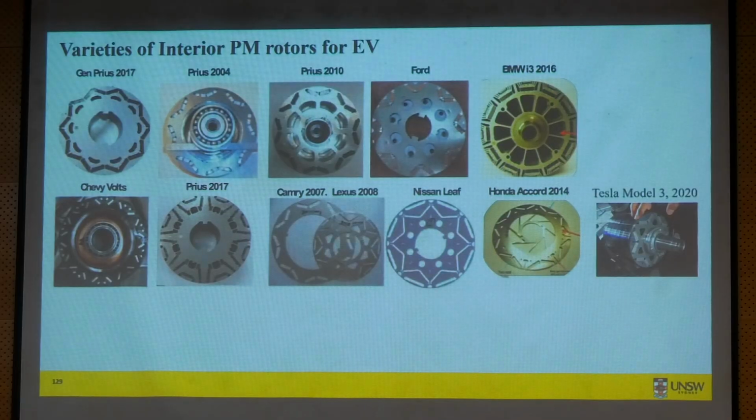They have specific objectives, and those objectives lead them to these types of designs, mostly for that region. You may see that V shape is becoming a norm, because it can provide the best flux concentration in the air gap. At the same time, it can give you the best possible reluctance torque. Okay, so V type has become quite popular.